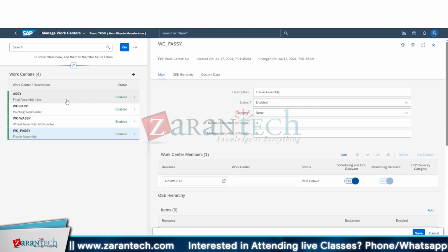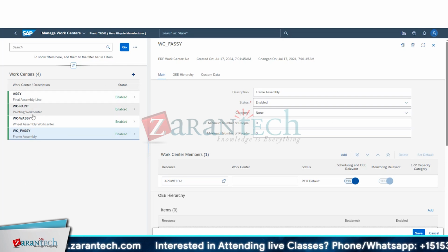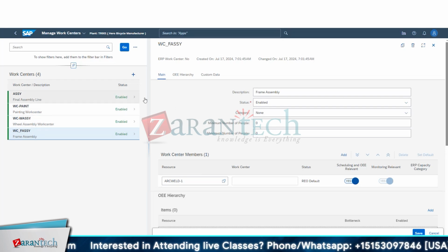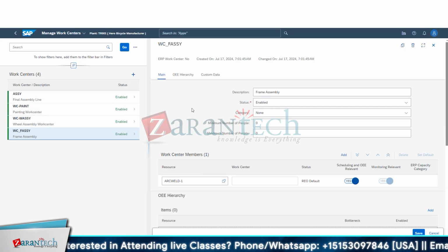So always be mindful of what you start, because deleting this master data once the order or any SFC has started and used these resources, work center or shift will not be possible. In the sense that you can change some data inside it, but if you want to delete the whole entity, that is not possible. So be careful about that.